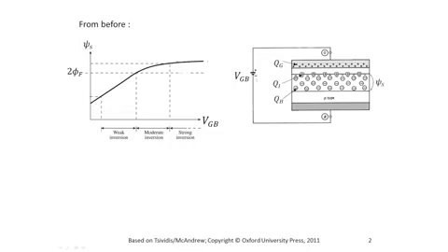and that it flattens out over here for the following reason. Once ψS becomes large enough, the electrons start piling up here next to the surface, so a very slight increase in ψS is enough to increase the electron concentration and QI a lot. So when you increase VGB, you demand a larger inversion layer charge QI, but a slight increase in ψS is enough to give you that QI. So ψS doesn't have to increase much, and this is why ψS flattens out for large values of VGB.